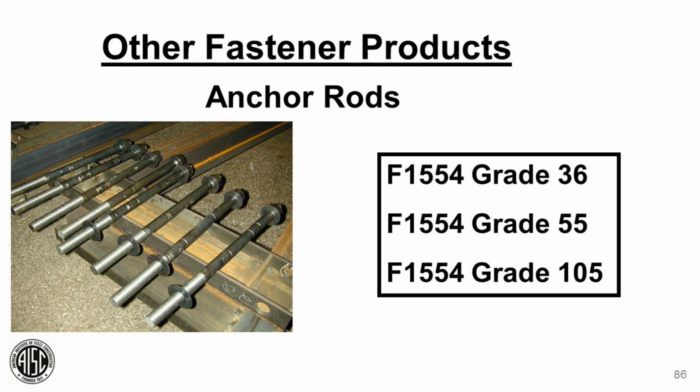All right. So another question about the specifying of anchor rods. Is the fabricator allowed to supply F1554 grade 55 with the S1 supplement, without the engineer of record approving, when the engineer has only specified grade 55 without the supplement? Well, the supplement only adds weldability to it. And I think it's to everybody's advantage to add the supplement to make sure it is weldable in case there is a problem with it.